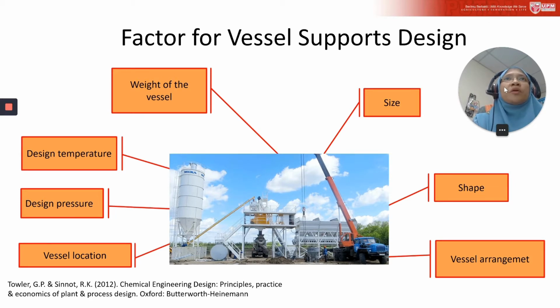The method used to support a vessel will depend on the size, shape, and weight of the vessel, and also on the vessel arrangement, design temperature, design pressure, and vessel location. When we talk about vessel location, sometimes the weather factor also affects our design criteria.